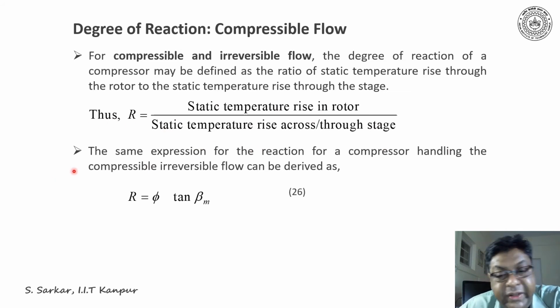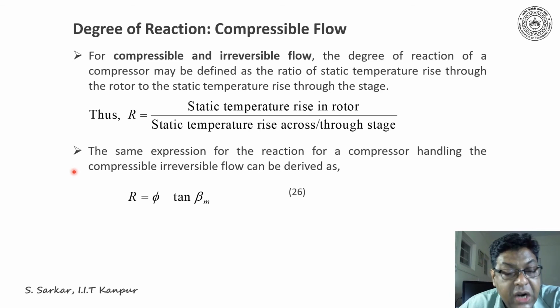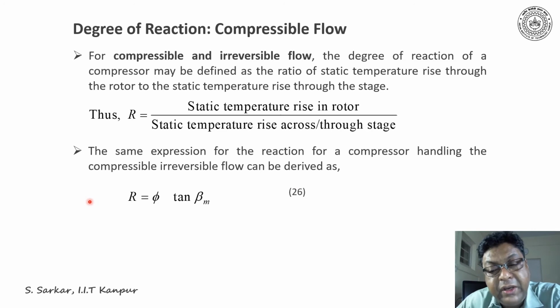It should be noted that we can arrive at the same expression considering the flow as compressible and irreversible, as R is equal to phi into tan beta m. Thus, equation 26 gives the expression for degree of reaction for both compressible and incompressible flow.